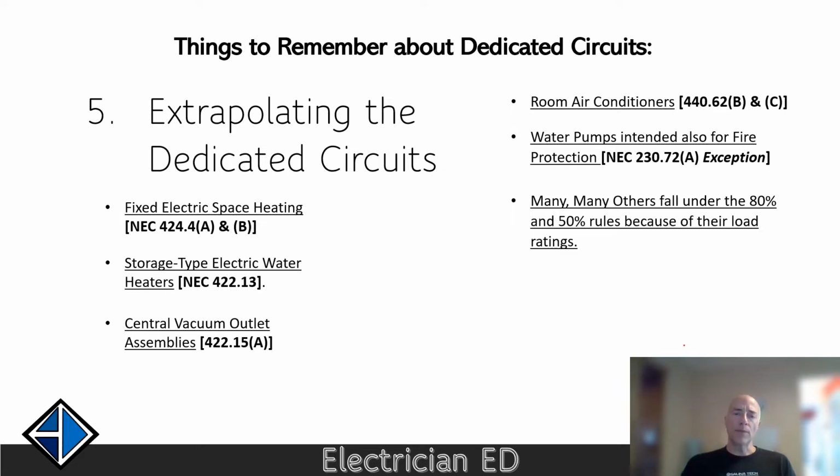Okay, water pumps are another one, if they're intended for fire protection. So this rule is really an exception for a special case. It's almost too technical to even be helpful in this discussion. But if your dwelling unit, in other words, your house or your condo, whatever, uses the NEC's special permission to have 2 to 6 disconnect switches.